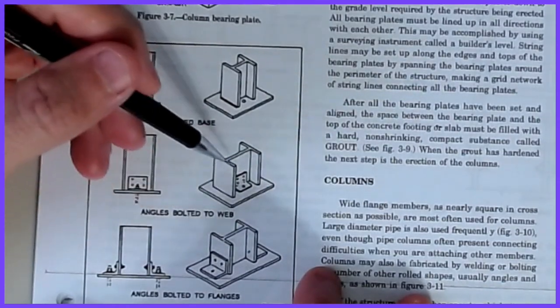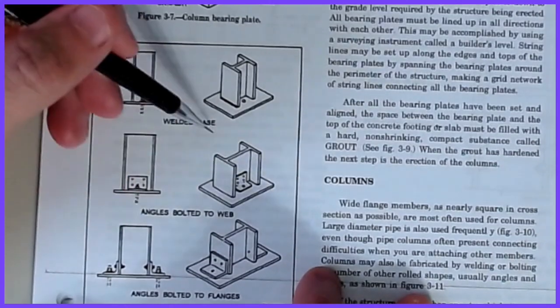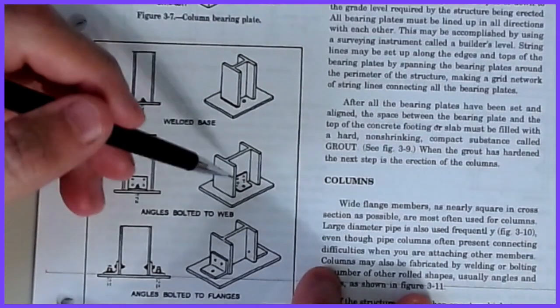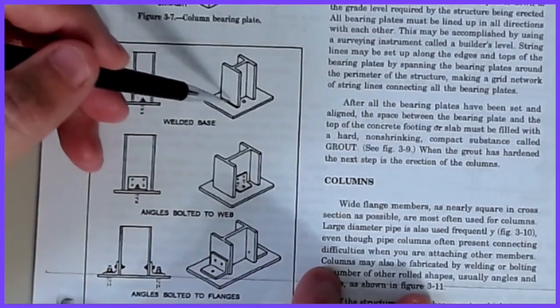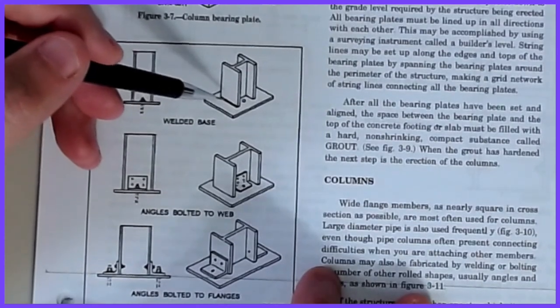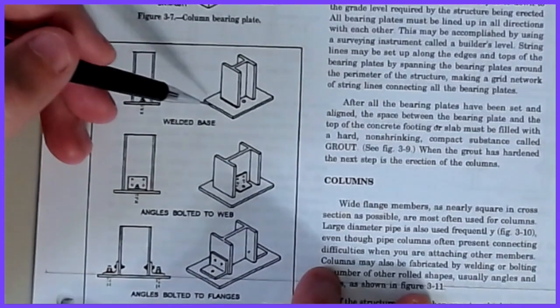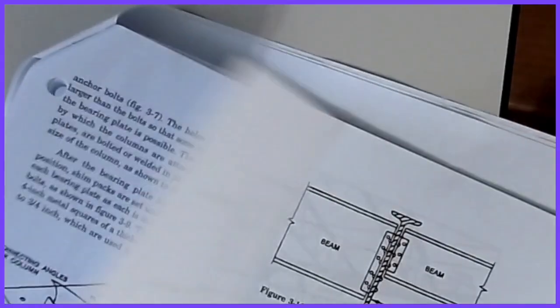It's just a bunch of fewer extra pieces that have to be aligned. Every time you drill a hole, there's a chance that it doesn't match on the member that it's going into. There's some potential for issues here. So my history has always been using welded base plates on those, but I'm not going to say that they're not useful with the other ones. These are just, to me, the more common that I've seen. So that's what I prefer on those. All right, so then we move into the columns themselves.